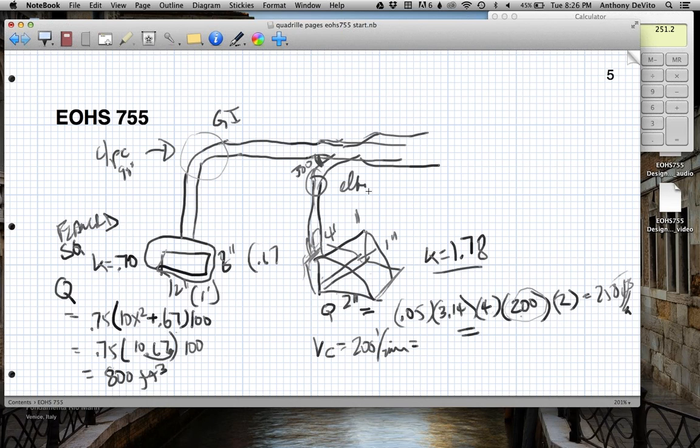But in order to get there, we got another elbow over here. Okay, and we're going to use the same kind of elbows throughout. 4-piece, 90 degree. Now we have this duct. This new duct, the main duct, is going to continue along to an air filter. Well, now we got a problem here. We have a fume here, and we have a particle here. So we're going to need some sort of filter that has two media in it. It's got a media filter, and it's got an activated charcoal filter, right?